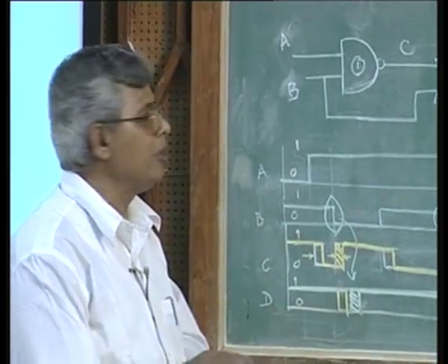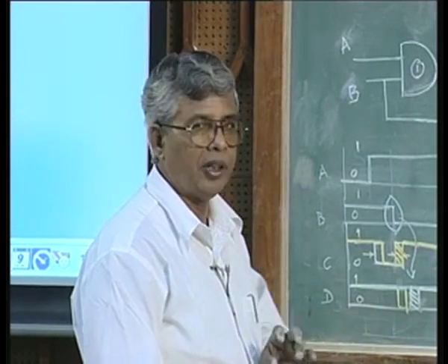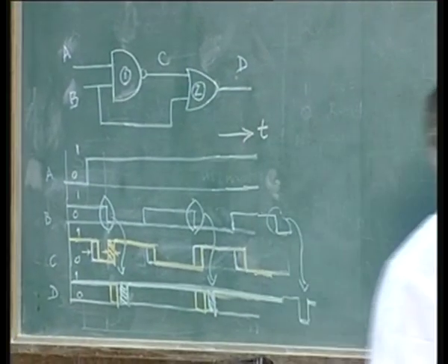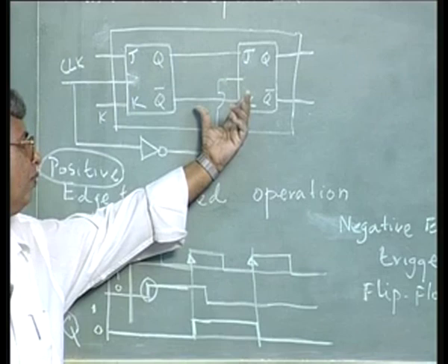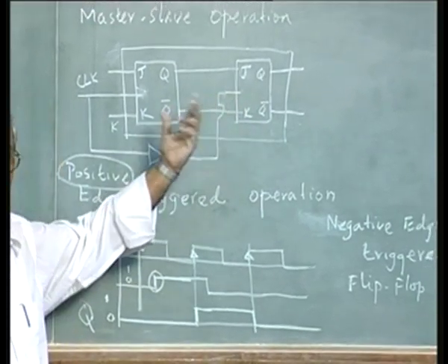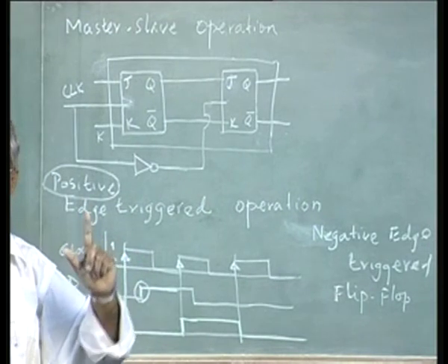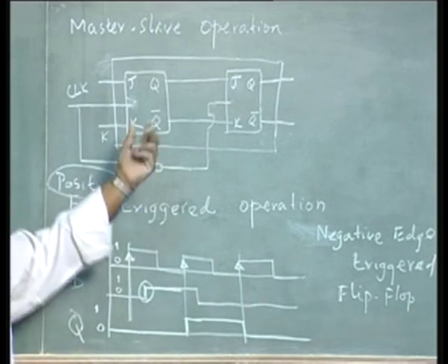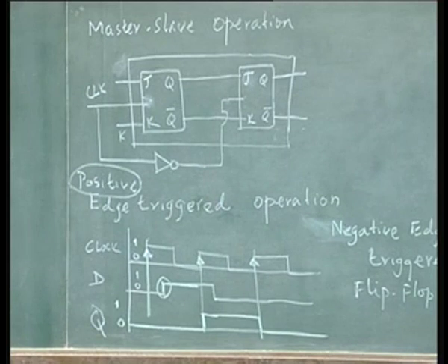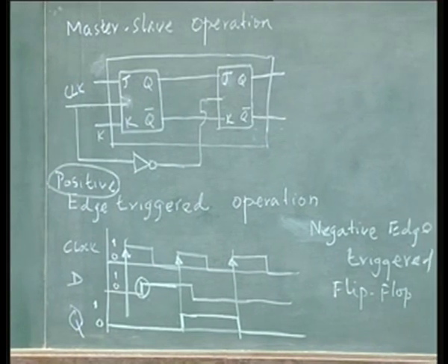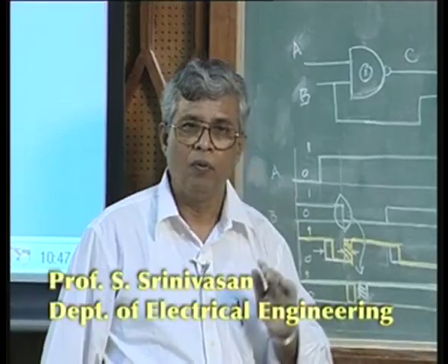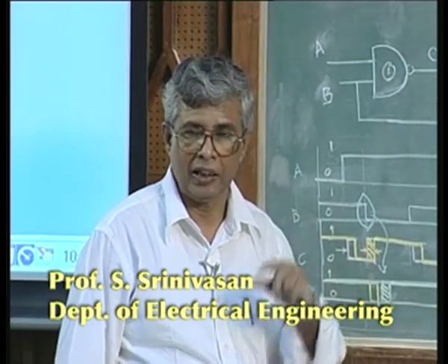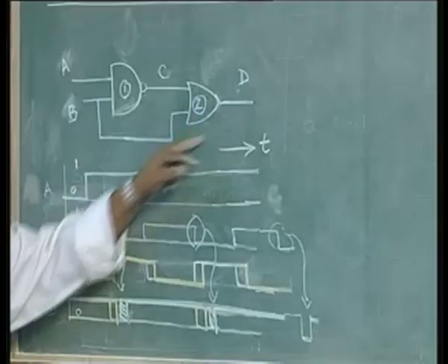Now, in edge triggered operation, what happens basically is, at each input of the flip flop, here we said simply the JK flip flop has the master slave flip flop with 2 identical flip flops. But in the edge triggered flip flop I said simply, it is very easy to say that there is only one flip flop, so I reduce the hardware. The speed of course is the speed of the propagation I said. Now, that is not all quite true. I need to add to the input of each of the edge triggered flip flops, whether it is a JK flip flop, SR flip flop or a D flip flop, to each of the inputs of a flip flop other than the clock input, a little edge triggering circuitry.